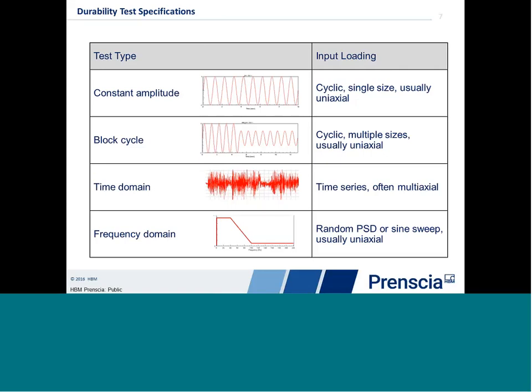Now, ENCODE has tools to help with all four of these types of test specifications based on fatigue damage equivalents and frequency spectra and fatigue damage spectrum and all kinds of neat things like that. If you look at our archived webinars on encode.com, you'll see we have webinars that talk about these other use cases in more detail. We're not going to dig into too much more detail about these right now. Just suffice to say that there are a number of different ways we may excite the device in the test lab. We need to decide up front whether dynamics are important and so on, and choose the appropriate route, and ENCODE tools can then help us define that test specification.